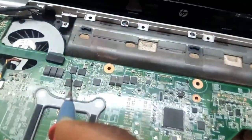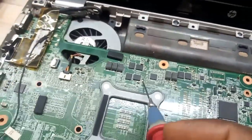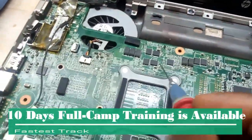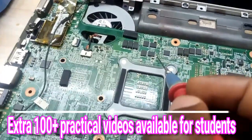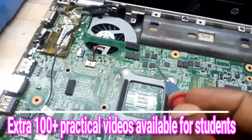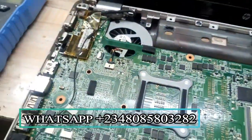Look at the top MOSFET of any PWM, like this place, this is a PWM. This is the inputting pad for separating 19 volt from getting to the PWM section. So I'll definitely have 19 here because this is the drain of the top MOSFET. So I'll jump 19 from this angle down to this angle, and let's see what we have.